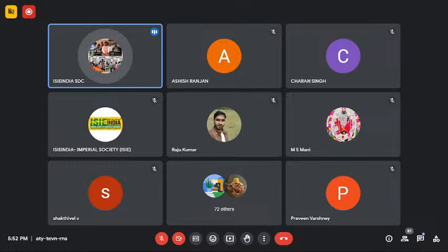And the contact breaker, contactors. So when you turn on the ignition, BMS will check the voltage, and the contactor turn-on procedure is there, because normally we are using 3 contactors for operating 2 wires. There will be a pre-charge operation. So for that, we need 3 contactors. So the contactor, when you are connecting the power with the power control unit, and at the same time when you are charging the vehicle with the external power source, another set of contactors. All this contactor operation we are doing with the help of BMS only.